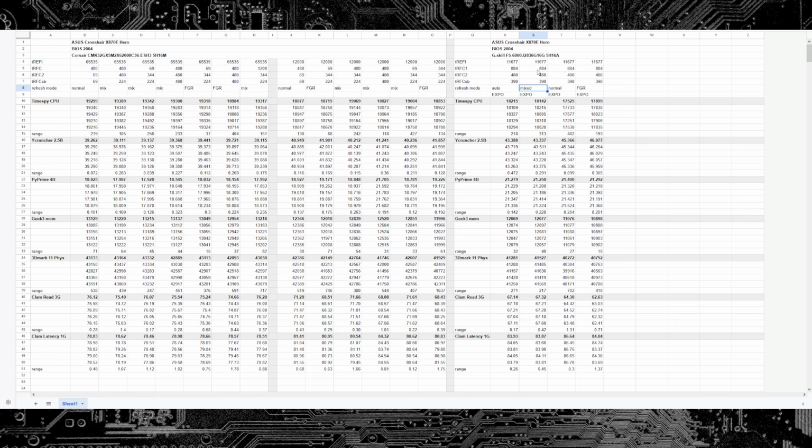I don't know the exact specifics of how AMD has it implemented, but when it switches to normal mode, it definitely uses a full-length refresh interval. However, it doesn't use TRFC1. And that means that when mixed mode goes into normal mode refreshing, it uses TRFC2, which is way shorter than TRFC1 is, and that's why mixed mode is always faster.